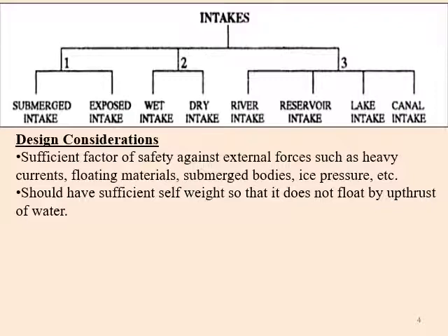So here heavy current is the main thing. Heavy flow or the upthrust force of the water should not make the intake structure float with the current of the water. So the self weight, the concrete weight, and with the water, the self weight of the structure should be sufficiently heavy. Accordingly, an engineer has to design the concrete structure for the intake.